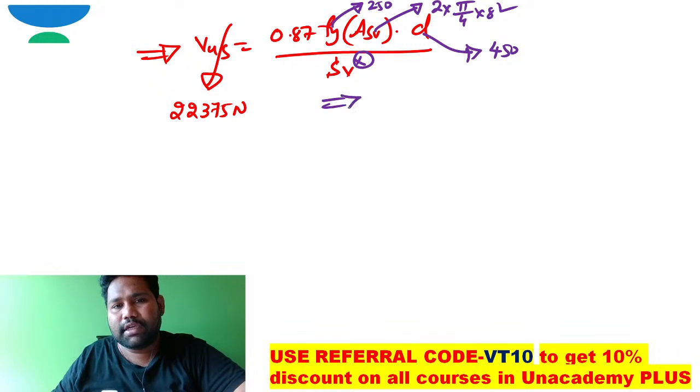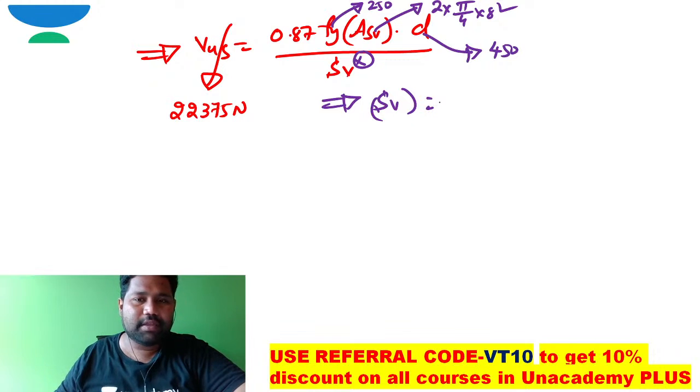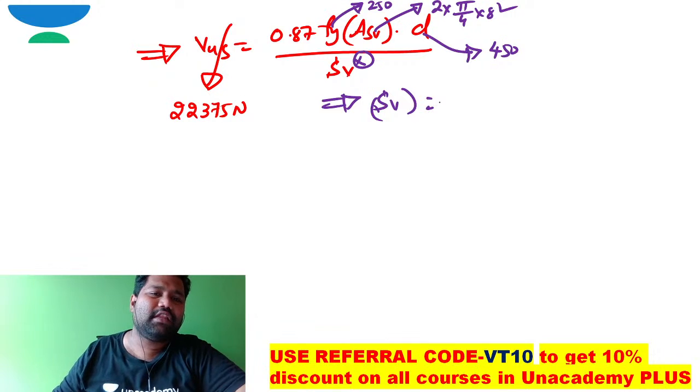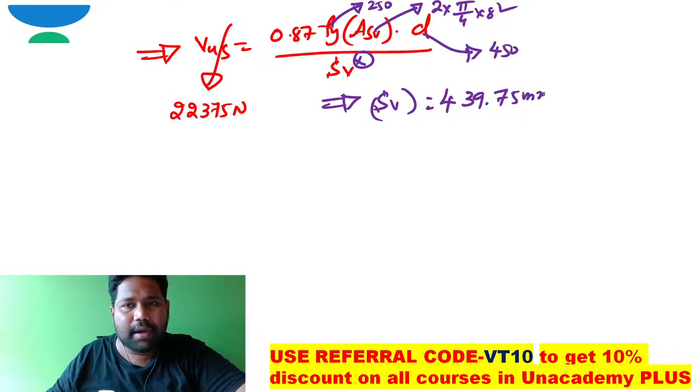Can you work out Sv, the spacing of the shear reinforcement, brother? If you work out the spacing, what will be the answer? You will get this answer in millimeter, because I had taken the force in Newton and distance in millimeter. So Sv is spacing now, which is 439.75 millimeter. But you cannot directly fix this option.